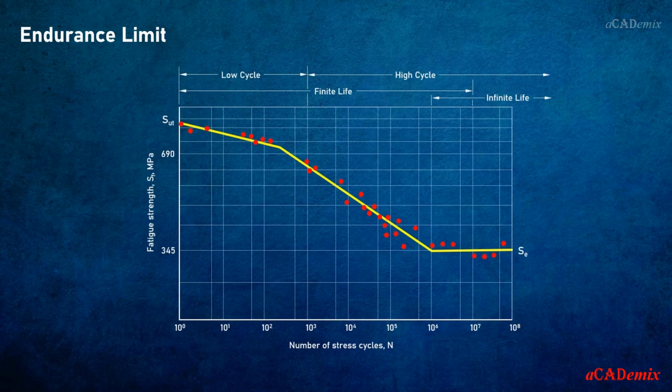We have already mentioned the term endurance limit. For the fatigue life calculation, the value of endurance limit is essential. So, what is endurance limit? It is defined as the stress range below which there is no crack growth and material shows infinite life under the cyclic stress. For preliminary and prototype design and for some failure analysis as well, we require a quick method for estimating endurance limits.